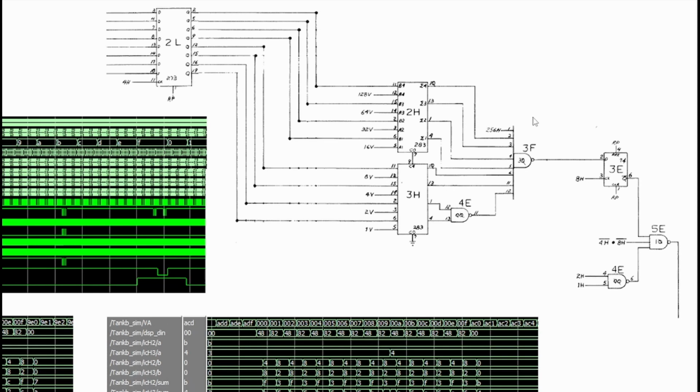So really it's only passing a 0 out during the H blank period at the beginning of every horizontal line, and then if the sum of these is FC, FD, or FE. Now the flip-flop here is clever because it filters the result to only be relevant when the right coordinate is FC, FD, or FE. We'll see it filters it only when the vertical coordinate matters, and the remaining circuitry here just makes the pulse output to be a particular duration. So this output of 5E becomes the main important output for the vertical offset circuit.